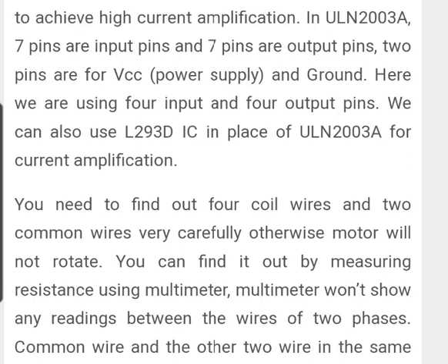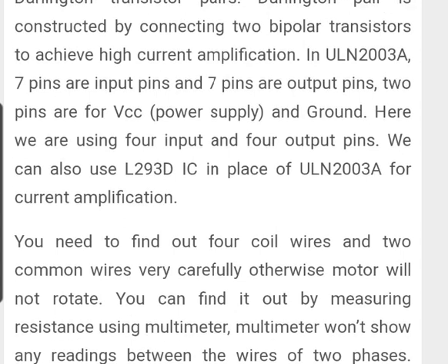We can also use the L293D IC in place of this ULN 2003A for current amplification. The basic use of the ULN 2003A current driver IC is current amplification, because the microcontroller alone doesn't provide enough current to drive the coil or the stepper motor. For that purpose, we have to use this current driver IC.